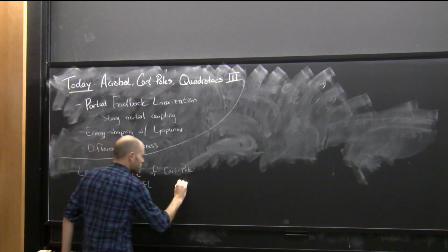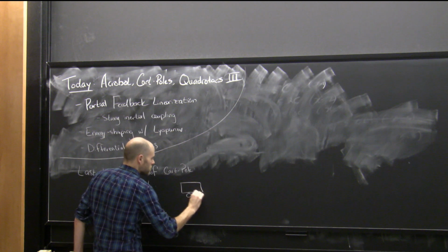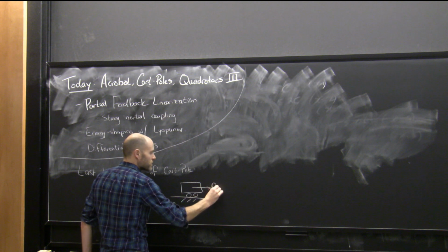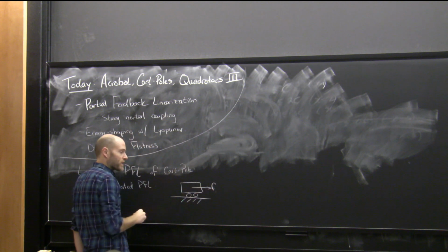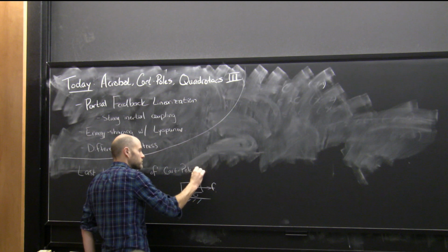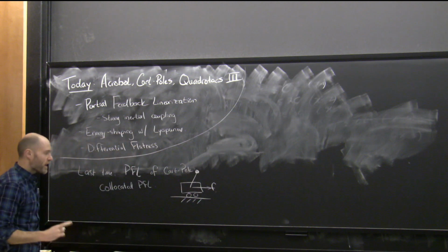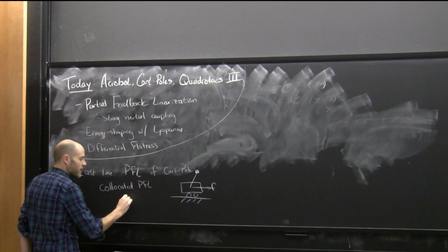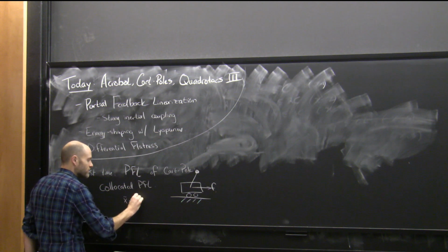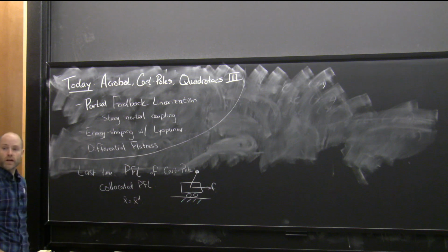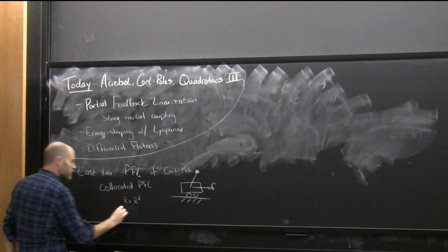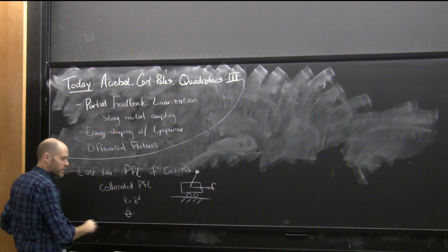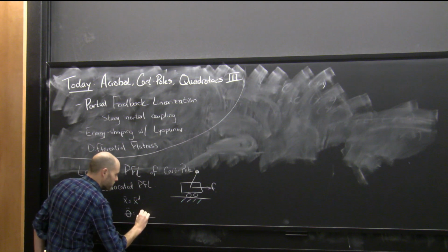For the cart pole system, since there's one degree of freedom, which is x, which has the motor pushing directly attached, it's not too surprising that we were able to change the dynamics into x double dot equals x double dot desired. And we were left with theta double dot doing something funny. I could write it down here, but it was nonlinear.